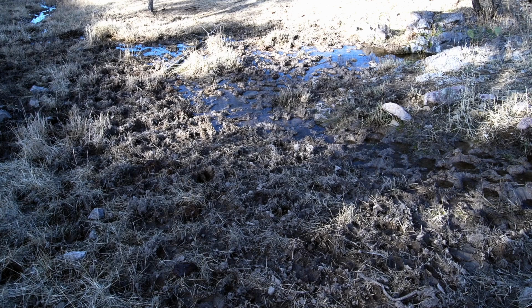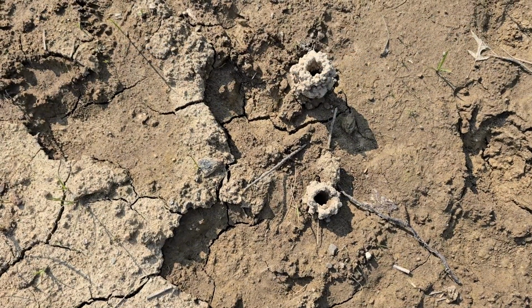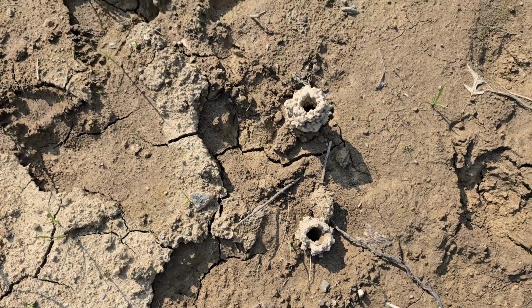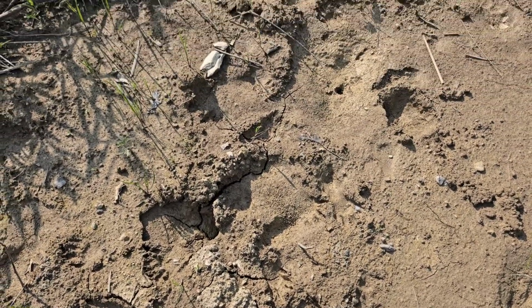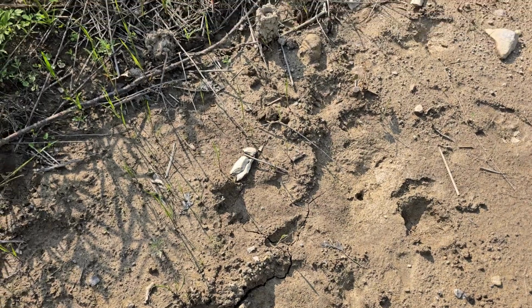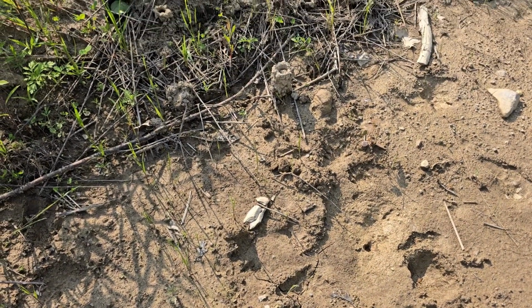The saturated soil indicates that water is flowing from the pond basin and under the dam. Finding crayfish chimneys in the dam or in the basin of the dry pond indicates that water is entering the crayfish burrows and flowing under the dam via a permeable layer of sand or gravel.